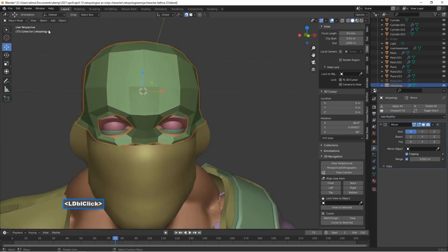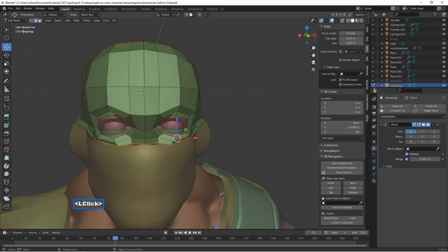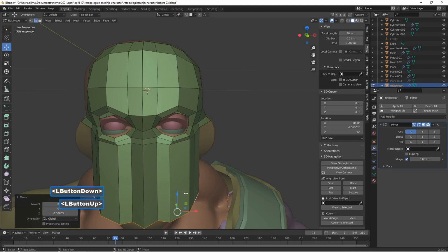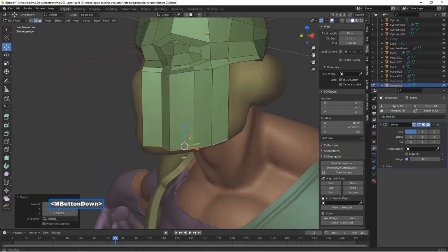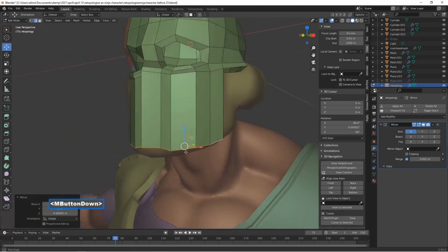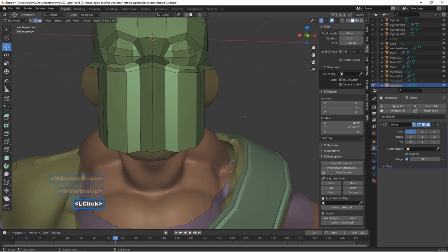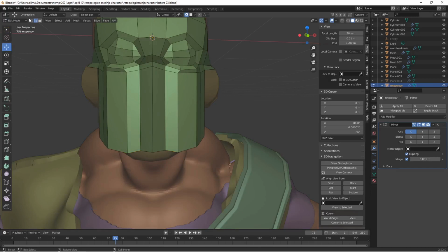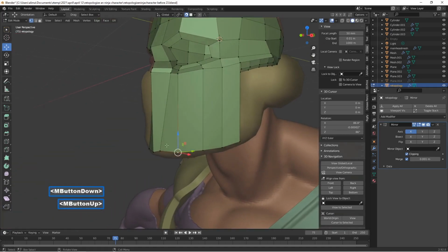I'm going to go to the upper left, go to object mode, temporarily turn off snapping, and go back to edit mode with this selected here. I'm also going to temporarily turn off clipping. I'm going to press E to extrude, right click, and push this geometry straight down. I'll left click, turn clipping back on, go back to the upper left, turn snapping back on, and go to vertex select. When I select this geometry and push this down, it'll automatically snap to the face.